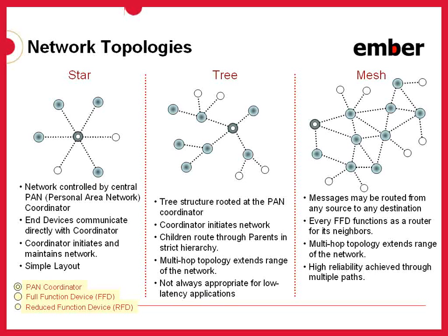In all three cases, the PAN coordinator is responsible for initiating the network, but only in the mesh topology is the PAN coordinator not necessarily instrumental to the routing of traffic across the network. If the coordinator is removed or temporarily inaccessible, we can see there are a variety of other paths that messages could take to get around the coordinator to reach the destination.